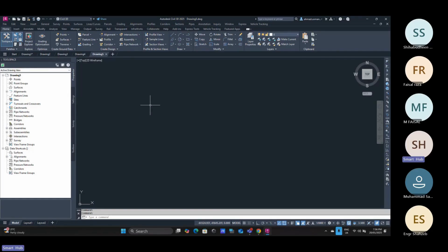All right. Let's get back to my topic. I've opened a new file, and here I need to add geolocation. Geolocation means bringing in Google Maps, Google Earth, or Civil 3D. So how do we do that? There's a command for this, MAPC.